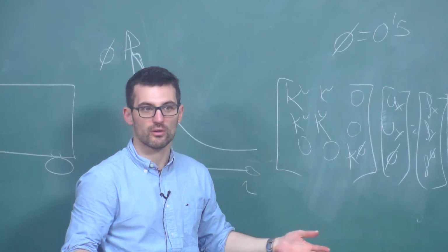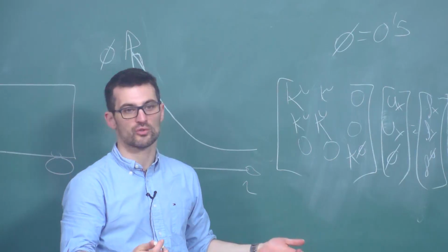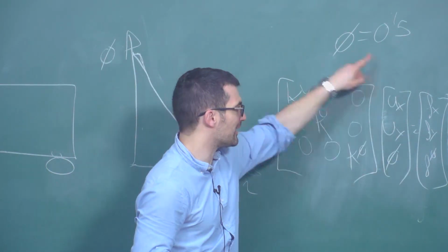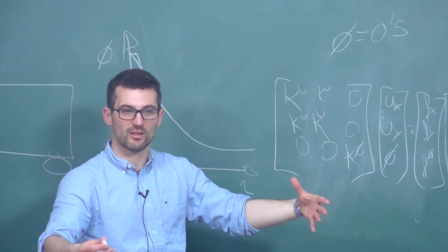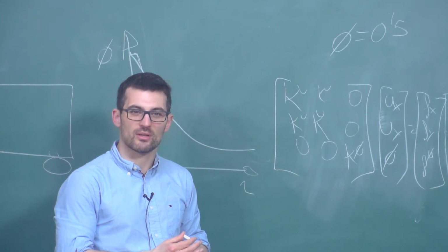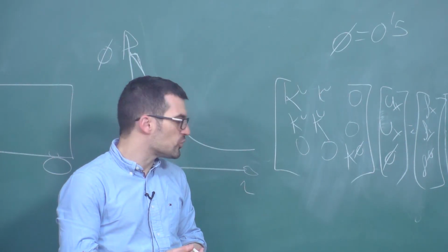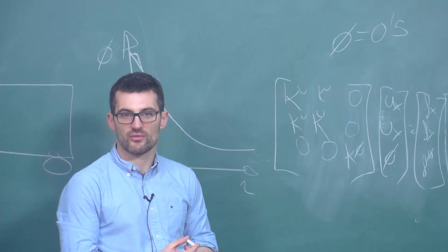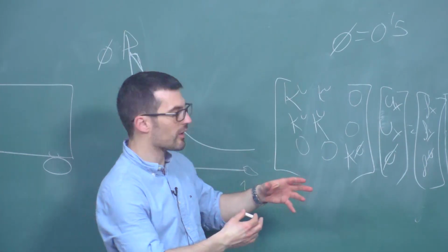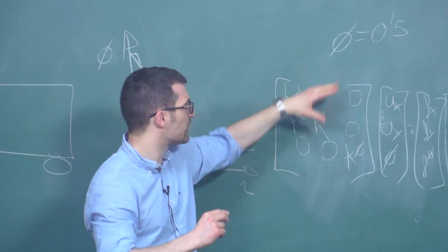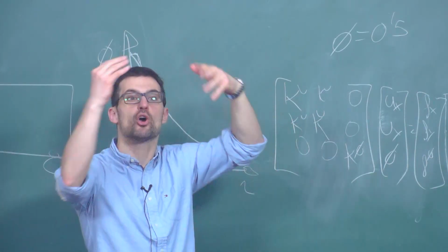This is what we all thought. So Abaqus will not be that useful. I mean, you'll still use Abaqus for meshing and pre-processing and post-processing. But at the end of the day, I need to define my own user element. And that's a bit nasty because in Abaqus, when you work with user elements, you cannot use most of the inbuilt features of Abaqus because Abaqus doesn't know what your shape functions are, where your nodes are. They don't know how even the geometry of the element.